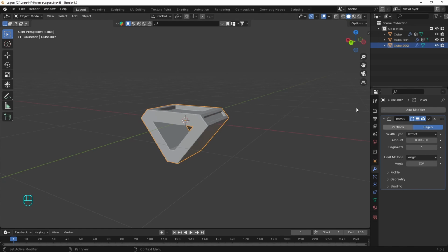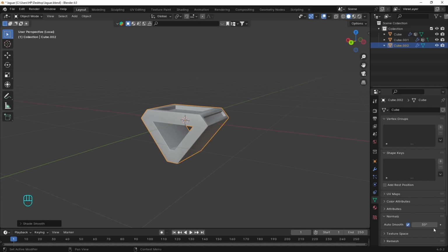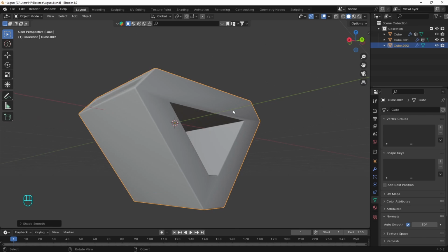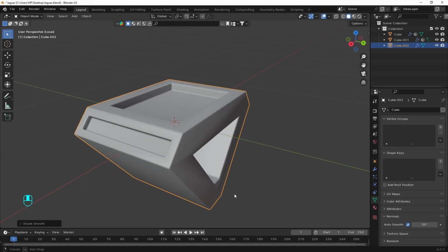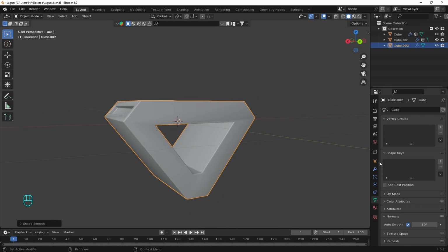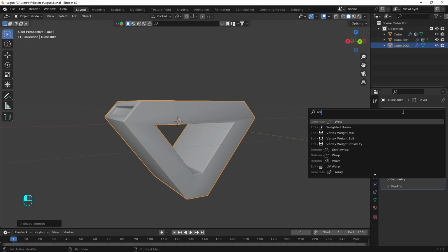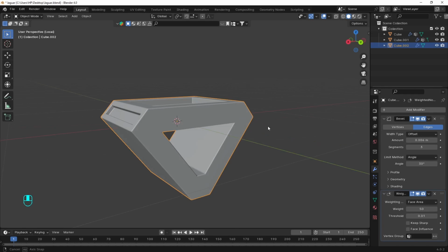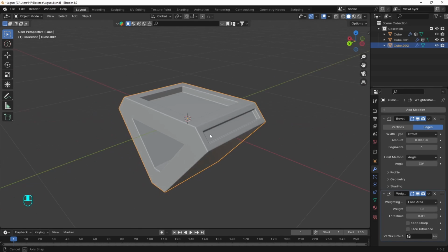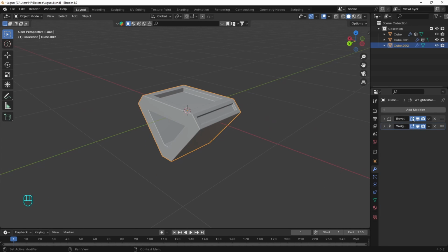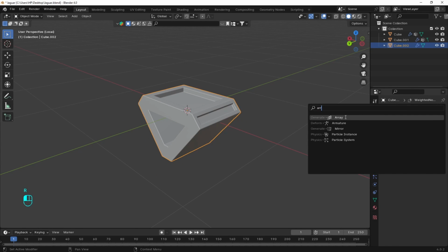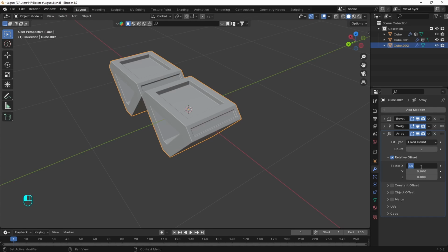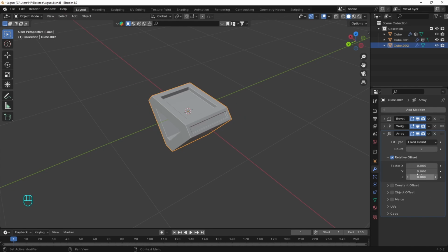If you're using Blender 4 like me, we can still shade auto smooth like that, which will enable the auto smooth option. The shading may look weird now, even if we created all quads based mesh, but we can solve this by adding a weighted normal modifier after the bevel. Array modifier to get a few more copies. We are using the Y axis, but this is not important here because we will array it along the curve, so change it to fit curve type.